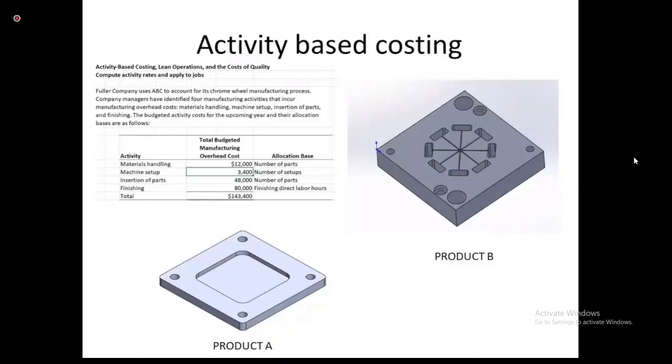And once you come to know what is the final product price, then you will start doing the optimization of the expenses for every activity. Now in most of the organizations, people don't work based on activity based costing. They will simply find out how much machining time is there on the component. So based on machining time, based on labor charge, based on machining time per hour rates, they will find out the cost of the product, which is altogether wrong.